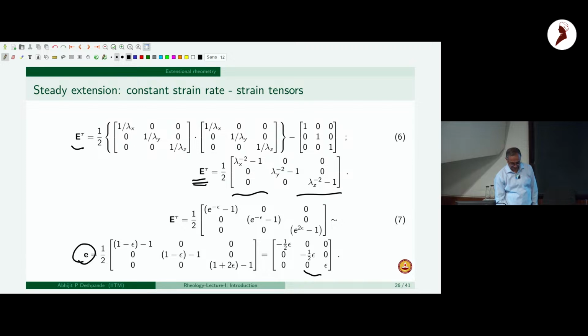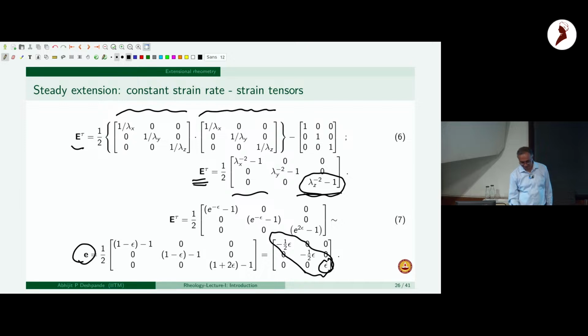This is what we learn in school books, where we say the strain is basically only epsilon. That is because we are using small deformation in the case of Hookean elasticity. But for large deformations, you have the nonlinear terms involved in how strain is measured. If you recall, this was a multiplication of the deformation gradient and the transpose of the deformation gradient, and then subtracting the unit tensor. When there is no deformation, this overall Finger strain tensor quantity becomes unity.